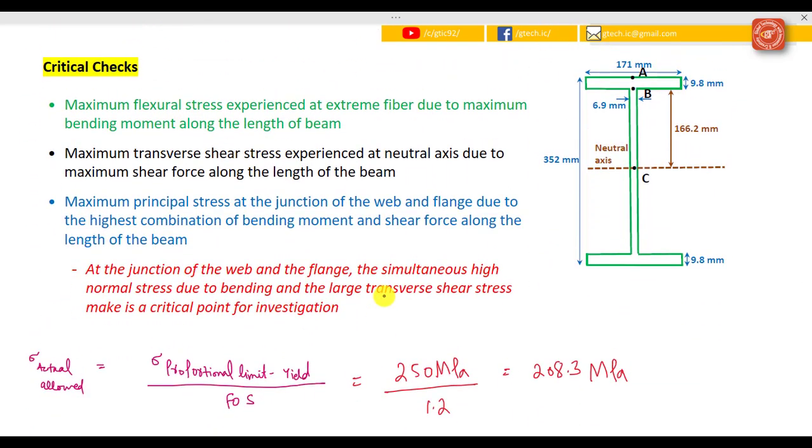We said that we were going to select this wide flange I beam to carry the load, and now we have to do our checks. So this is the beam cross section that we have selected. I have drawn a diagram of that cross section from the reference. I wrote the values for the depth and the width, etc. Because of symmetry, the neutral axis lies in the center.